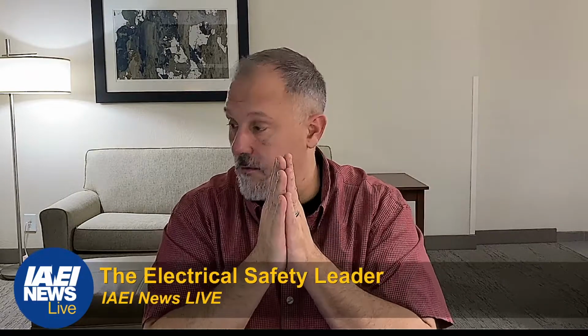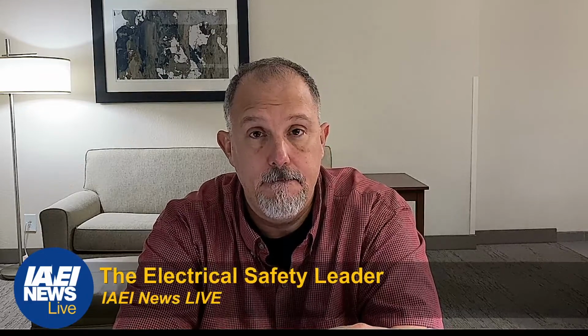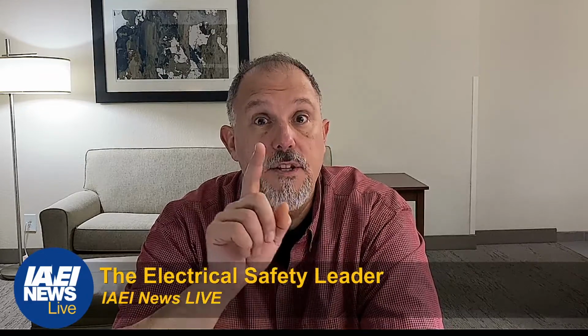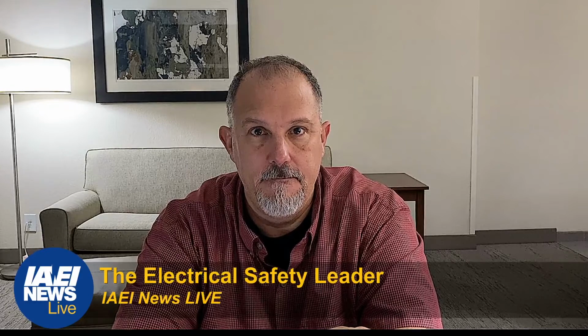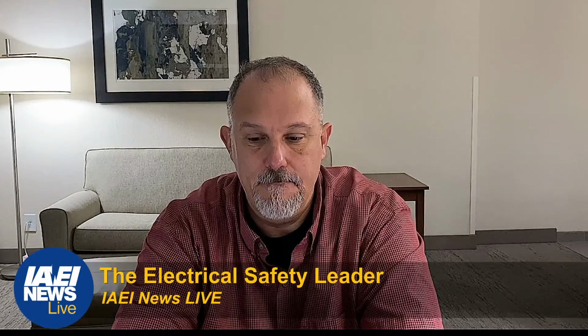Now what we'll do in our next session, we're going to pick our overcurrent protective devices. We'll calculate incident energy. And then we're going to selectively coordinate those overcurrent protective devices. And then we're going to recalculate incident energy.